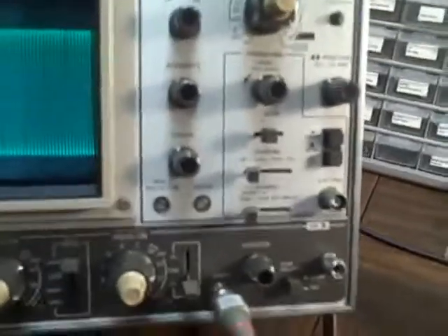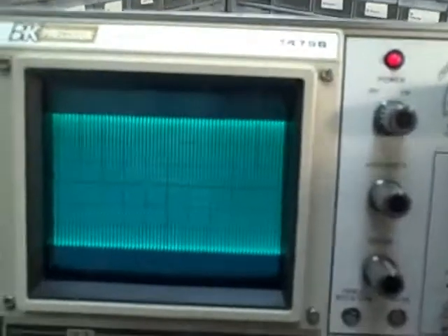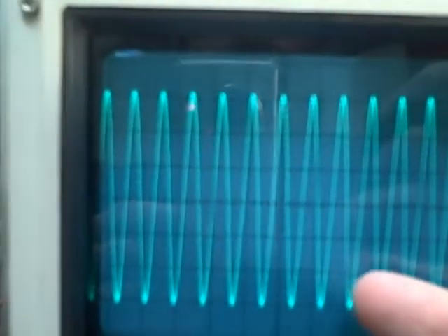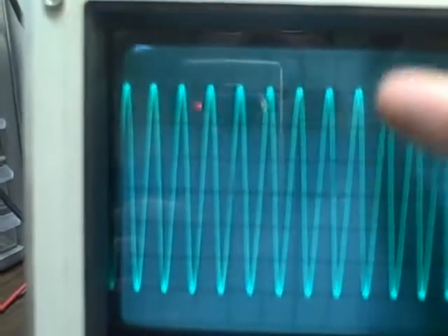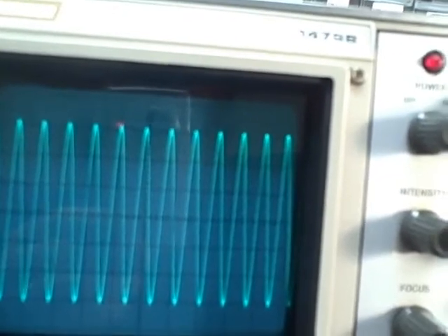We are also on the 10 millivolt per division scale, and we are at our full scale right now, and I'm going to multiply by 5 here so that we can see the waveform better. But what we see is we are running down 1 division. We are plus and minus 3 divisions, or 6 divisions total, whereas the 100 megahertz scope was running 8 divisions. So we've lost 1 division. But again, this is 30 megahertz that we're reading, and this is the limit of the scope.